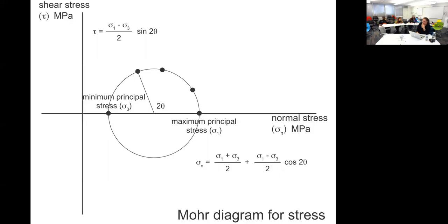And we draw a circle there to represent basically shear stress going positive, which is going to the left, and shear stress going negative, which would be going to the right. But there isn't really negative shear stress. It's just the same shear stress, or same magnitude, acting in the other direction. And so that's why we multiply theta by 2 so we can go full circle in this plot.